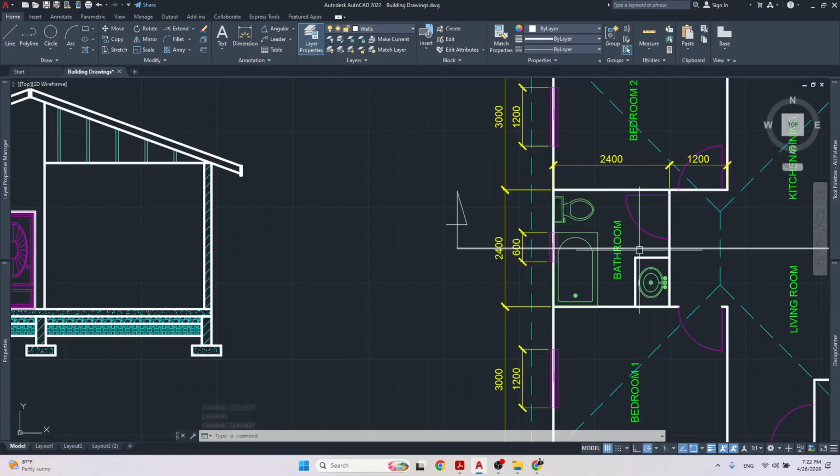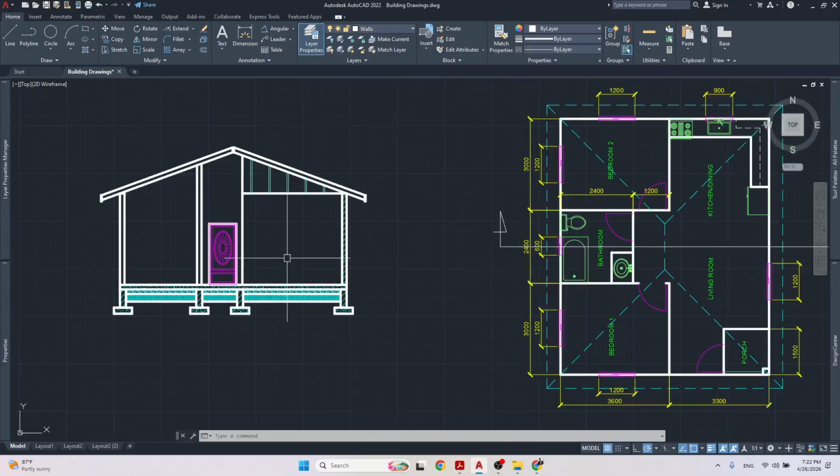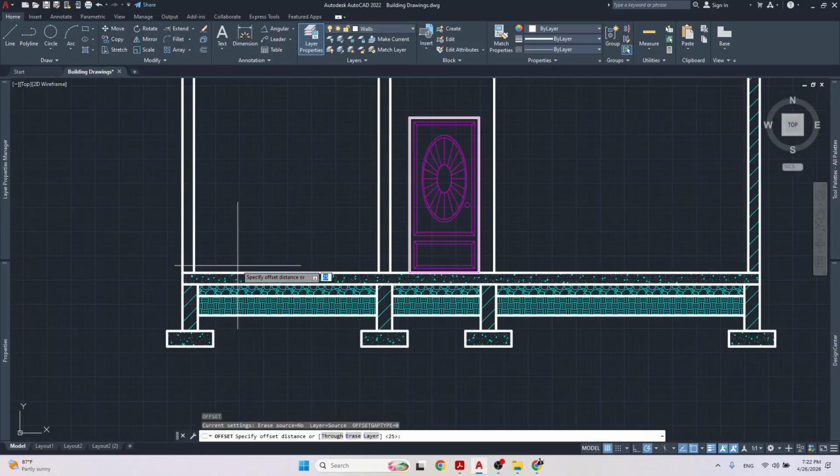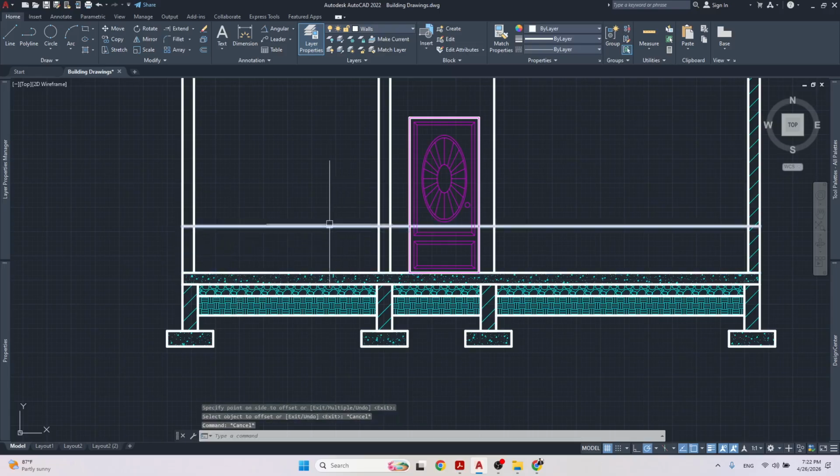All right, so if we are here, then we are in front of the sink, the basin, so we won't see the basin. This door is closed and we won't see it because we're not cutting through it, we're just cutting through the wall. But we'll see the toilet, and we'll actually be cutting through this window, and we'll also see the tub, well, the part of the tub that we're cutting through. So let's say 2 feet off the ground, offset 600, like so. That is where the tub would be.